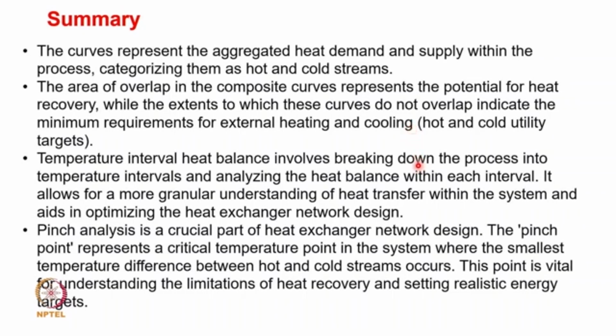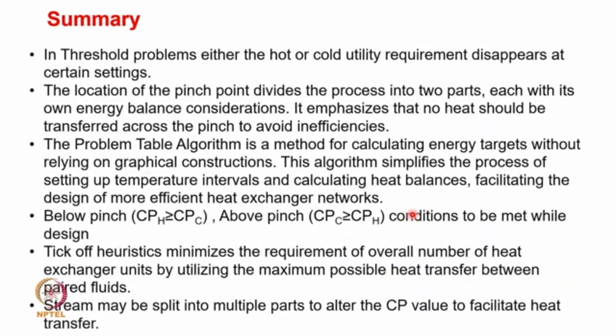The temperature interval heat balance involves breaking down the process into intervals and analyzing the heat balance in each interval. This allows a more granular understanding of the heat transfer within the system and aids in optimizing the heat exchanger design. Pinch analysis is a crucial part of heat exchanger network design. The pinch point represents a critical temperature point in the system where the smallest temperature difference between the hot and cold streams occurs. The point is vital for understanding the limitations of heat recovery and setting realistic energy targets.